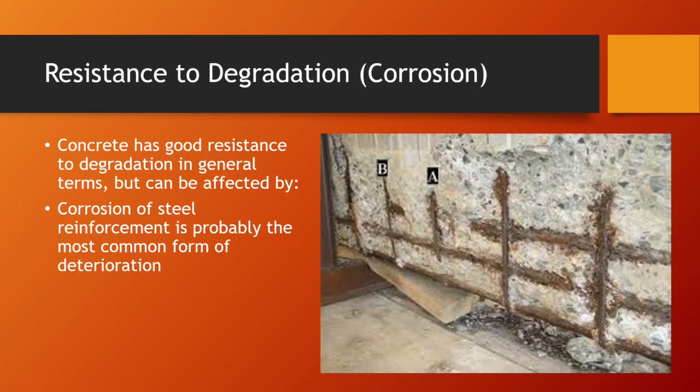Okay, and obviously once those rebars are exposed, you're in serious danger of the structure deteriorating very, very quickly as a result of that. The steel bars are there for a reason. If they start to rust and start to deteriorate, then obviously that structure is getting weaker and weaker. And guess what? It's happening at the base of that wall or that slab. So, you know, it wouldn't be the worst risk at all if it was at the very top. But certainly at the bottom, it's bearing all the load. So that's why this is incredibly important that we understand this better.